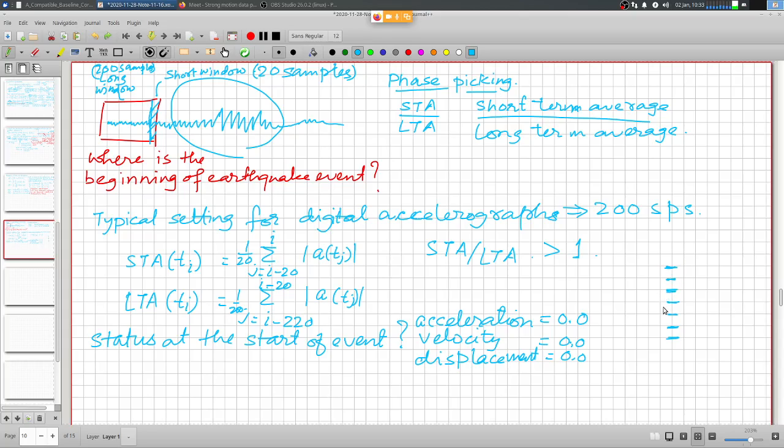So this complete bit level, whatever the total number of bits, 16 bits or 18 bits, will be the total range that is divided into that many configurations, and there will be a certain quantization that will be the least count. Our accuracy is only half of this. That's the resolution. We cannot resolve anything smaller than half of this quantization level.